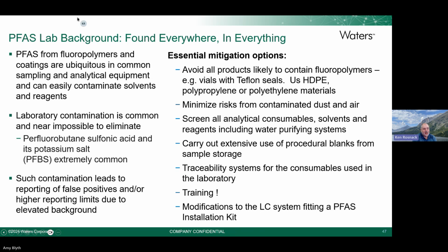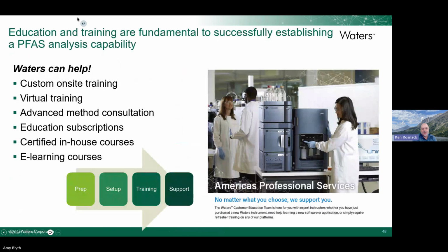And then in the lab, things we didn't talk about is, the solvent lines for the LC are going to be replaced with PEEK tubing or stainless steel. Stay away from deactivated syringes because you're just going to contaminate your samples. So that's enough about all the contamination. We'll keep going and finish up.